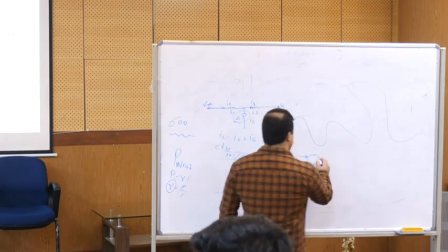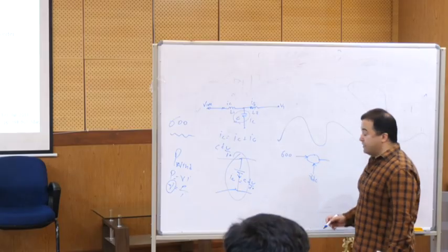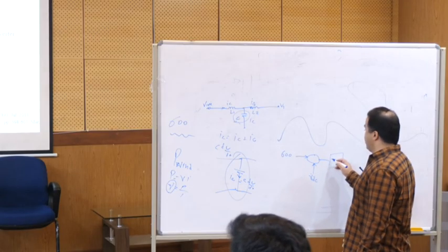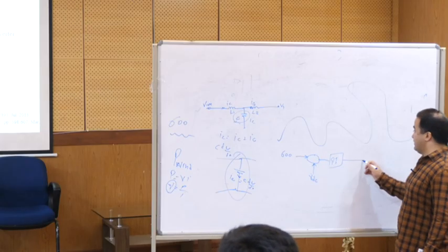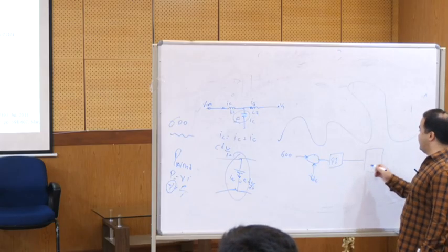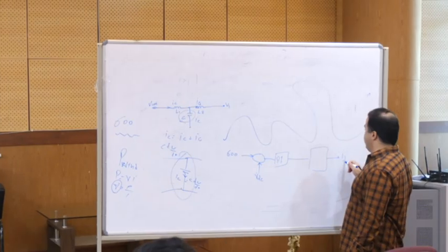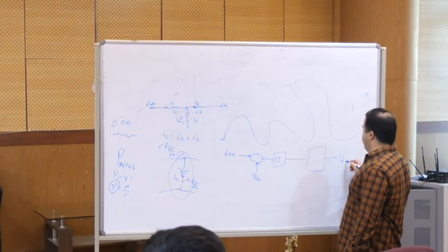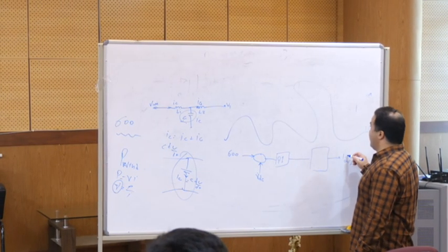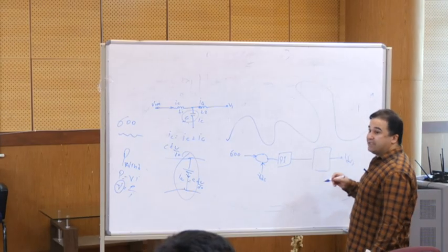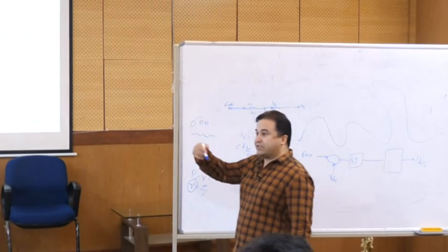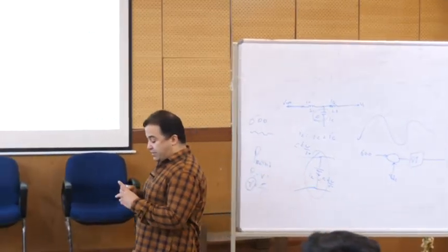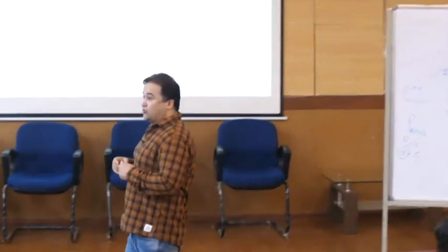So we have some problem here. Then the compensation by a PI controller is needed. And then you have some equation which creates an ID for VDC. This ID for VDC can be added to the control loop of the current, and after the transient time, we reach the regulated DC value for the DC side.